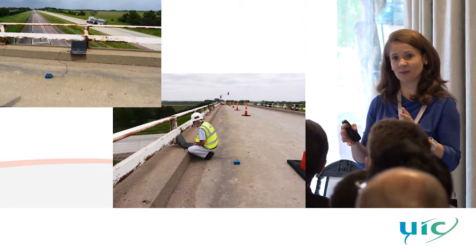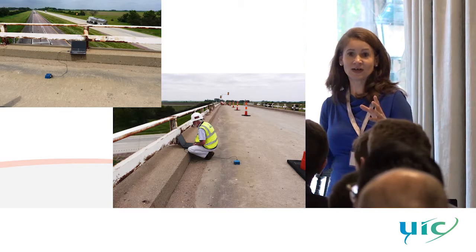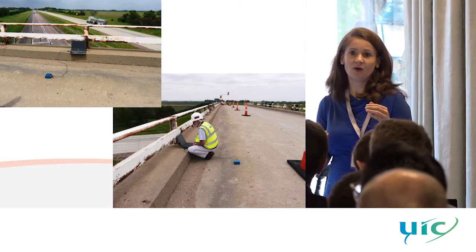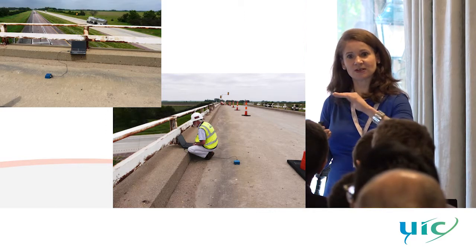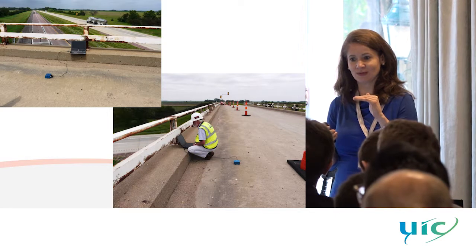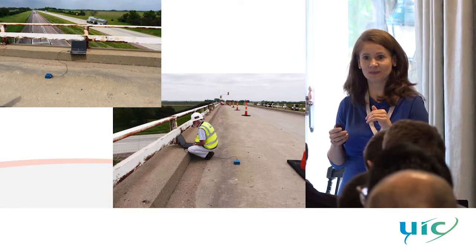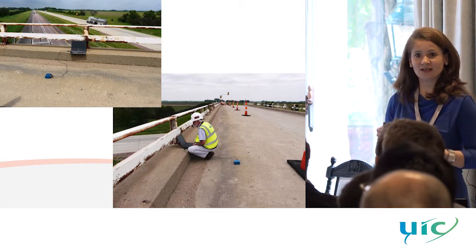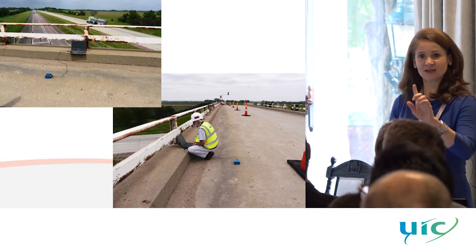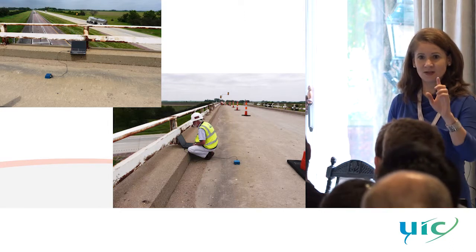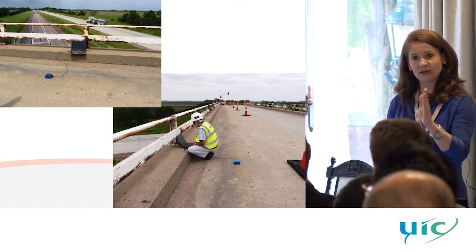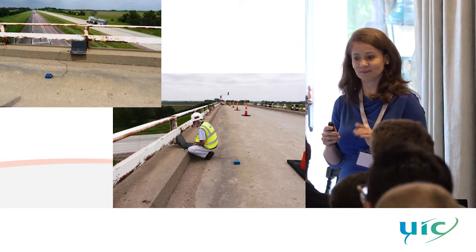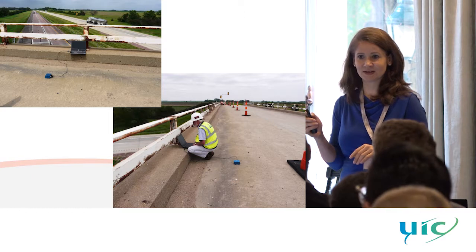So the background vibration gives us a very clear picture of the structural frequency response. It is like a footprint. Unless something changes in the bridge, the frequency spectrum won't change. So it would tell us the key frequencies up to 1,000 hertz.